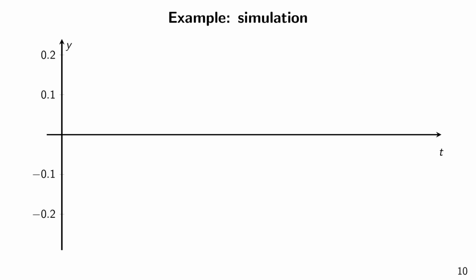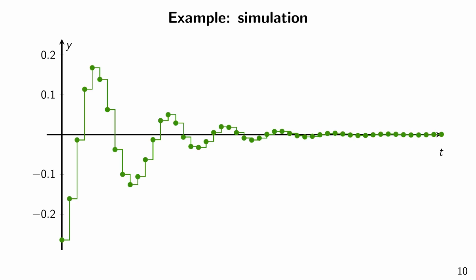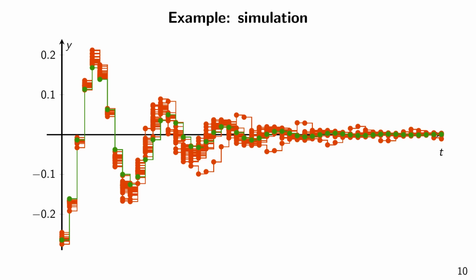Let's simulate the uncertain Lurye system in the time domain to further illustrate the results. For this, we use the nonlinearity obtained in the uncertain case. When we run the simulation with the nominal system, we see that the output oscillates but ultimately settles to 0. These are the results of the same simulation with 50 random samples of the uncertainty.